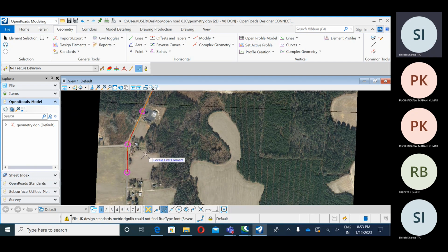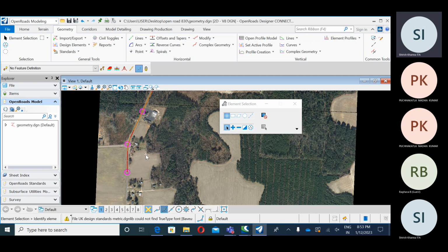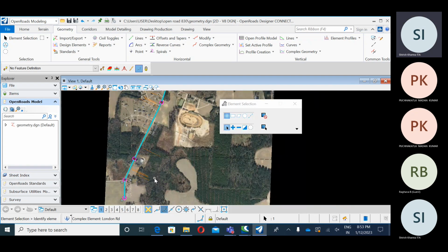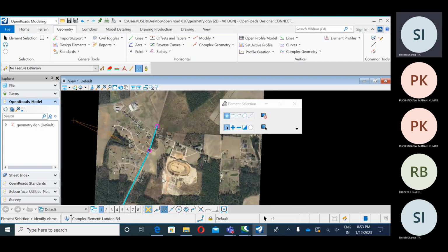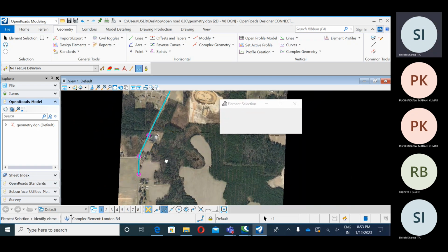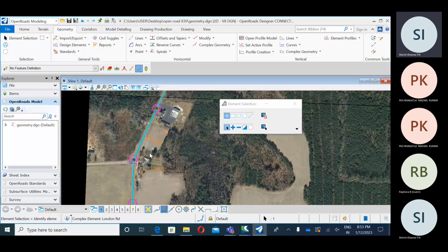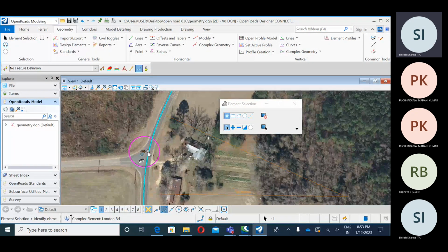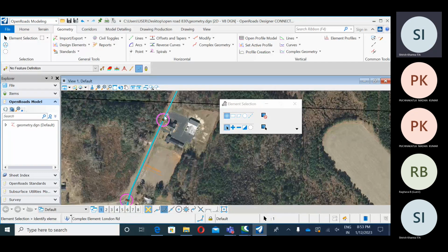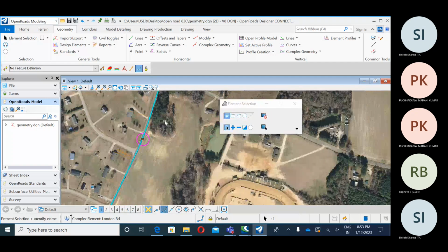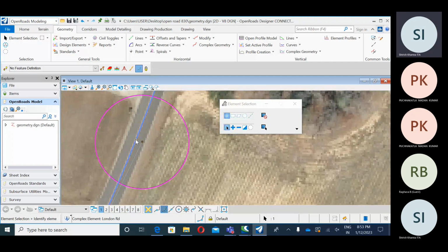How do we know it is completed? Now you are going to select it and hover on it. You see, it is selected completely in one click. That means this is converted into horizontal alignment. Now you can see the data on it also. If you want to change, I told you yesterday also, we can change anytime. You want to add a point, see, here we have that point. You can add it, you can change the radius. Any movement you want to change, here also we have that point. Here also we have 2 points. See, we can change anytime.